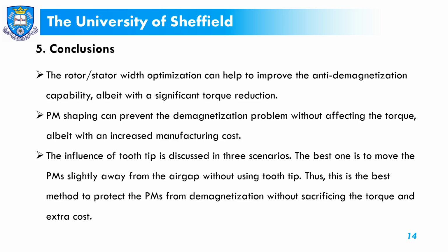The influence of tooth tip is discussed in three scenarios. The best one is to move the magnets slightly away from the air gap without using tooth tip. Thus, this is the best method to protect the magnets from demagnetization without sacrificing the torque and cost.